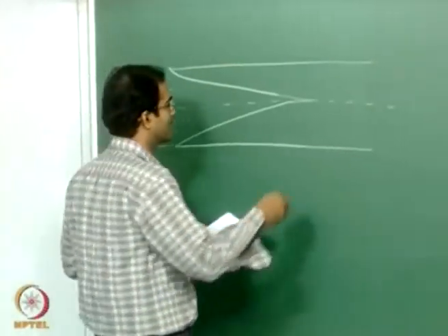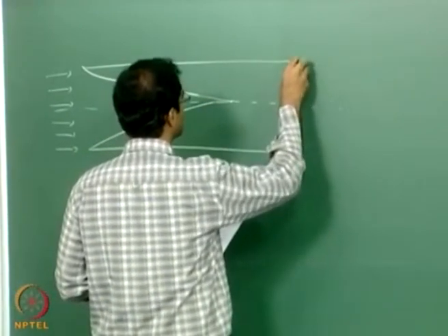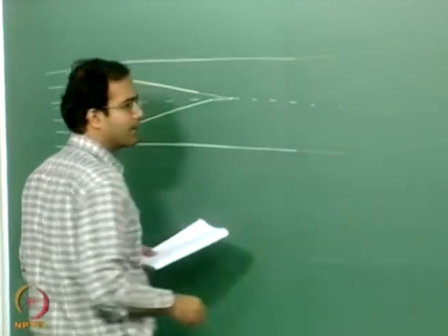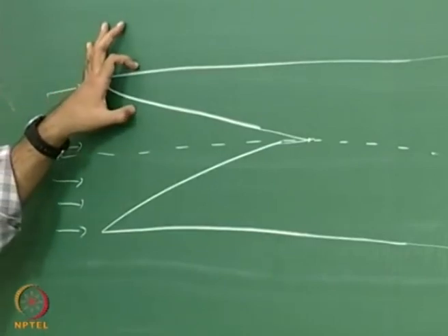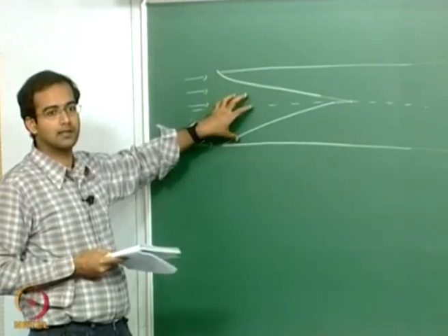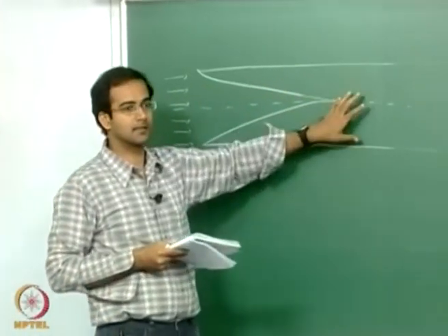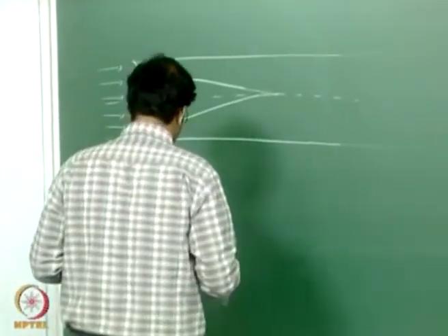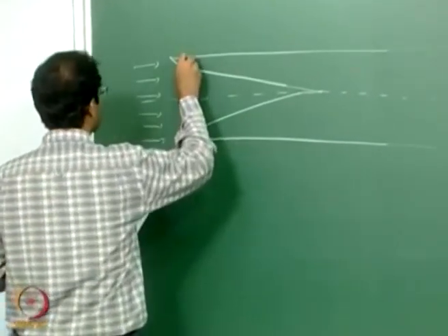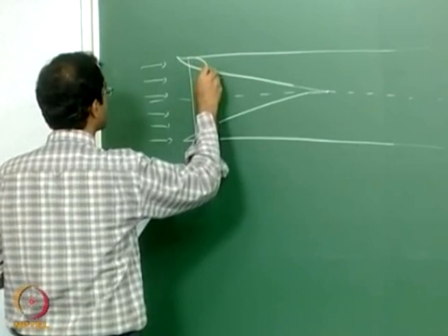Okay, so exactly at the center the two boundary layers will merge, and after that the region whatever you are looking at here is completely dominated by viscous effects. Whereas at the inlet you have a very small region close to the plates where your viscous effects are important, outside still the potential inviscid flow theory is valid, whereas once the two boundary layers merge, in this particular region everything is viscous dominated. Okay. Now if you look at how the profiles are drawn, somewhere at the inlet you can have a profile something like this.